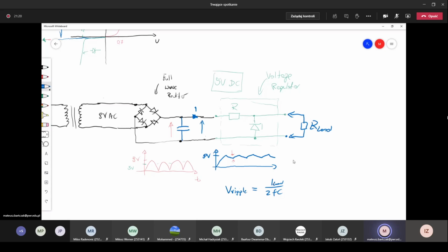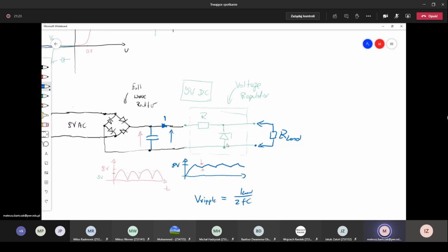And now, how will it work? We can see that this Zener diode is configured in the reverse configuration, because here we will have plus. In between those 2 points we will see some voltage with the ripple, always around 9 volts, and here we will have the ground.